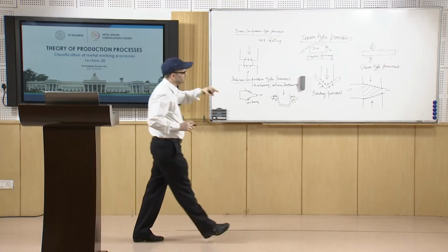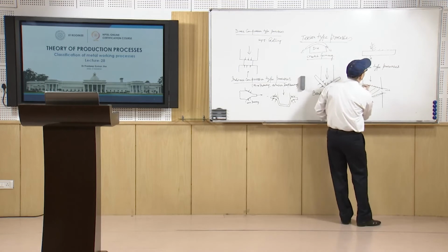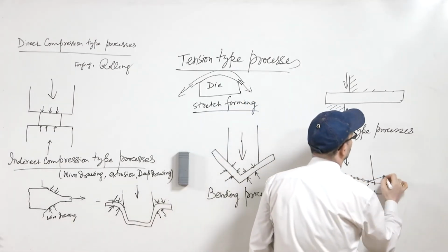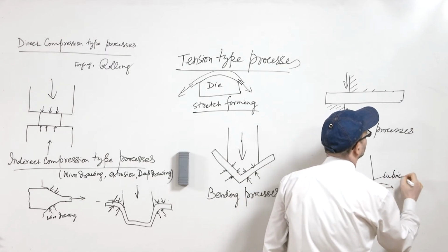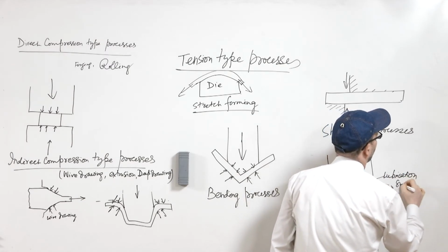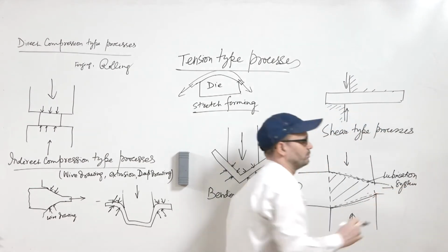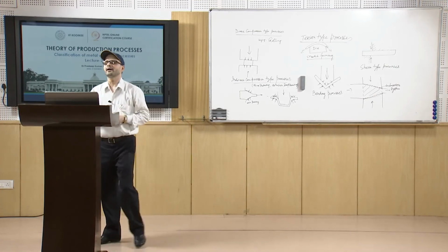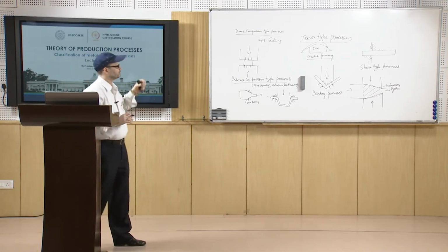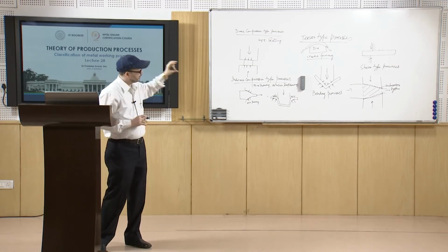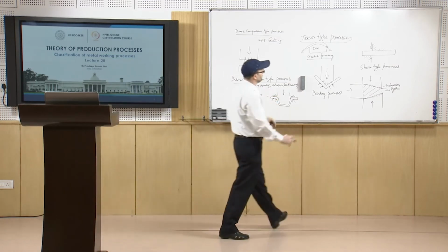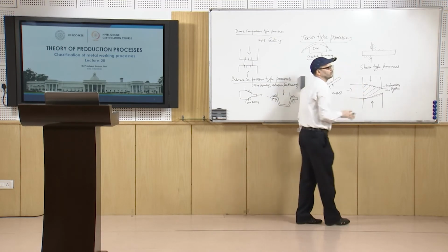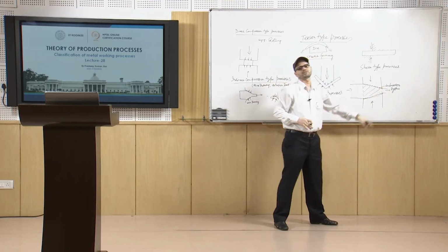You have this area where the lubrication takes place, and there will be movement. So you have this as the lubrication system. You will have friction acting there, and that will assist. So even the friction which acts here helps in getting the deformation. You will have the frictional forces because of which the material will go into this cavity.